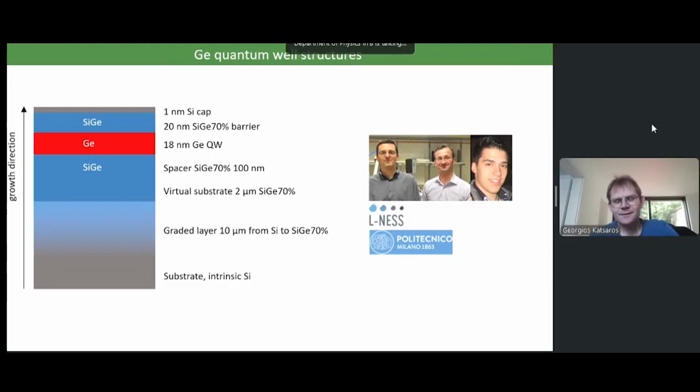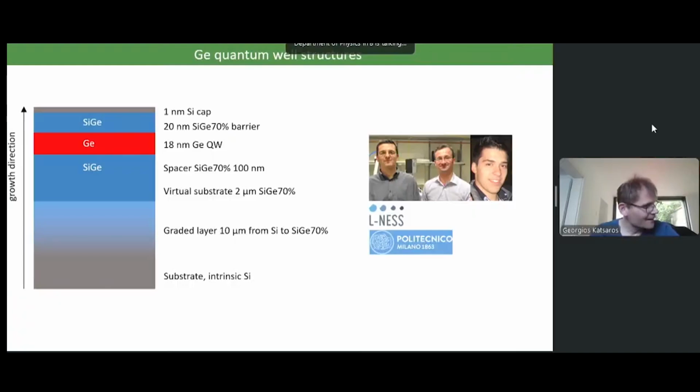Absolutely. A bit on the device turn-on characteristics. I saw that you used an ALD oxide, which of course is not here in the heterostructure. But is that oxide really needed? Sorry? Is the oxide really needed, or could you have put the gates directly? So the difference to gallium arsenide is you don't have a Schottky barrier. So there is the risk of leakage, or at least we never managed to have a gate on top without getting leakage if we don't have an oxide.